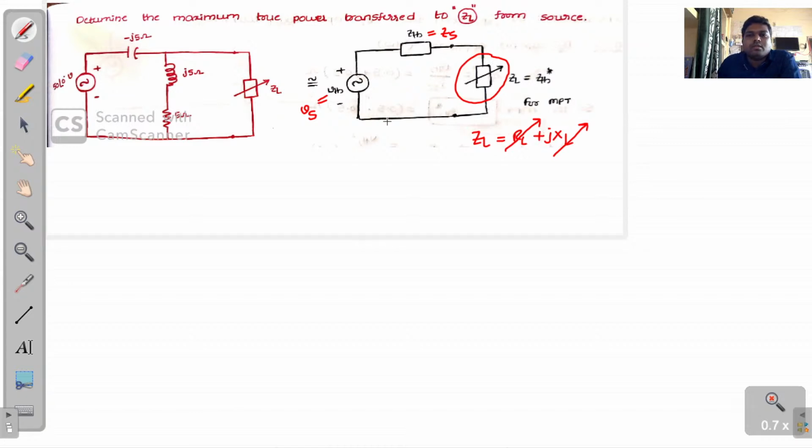Okay, now first, this end, you can remove this and indicate these a and b terminals here. For your understanding, remove this ZL first. Then you can find a single equivalent Thevenin's network for this particular given network, right? So first you can draw the circuit as it is.